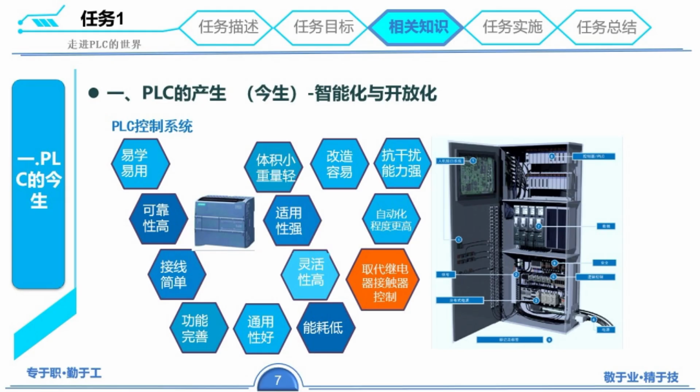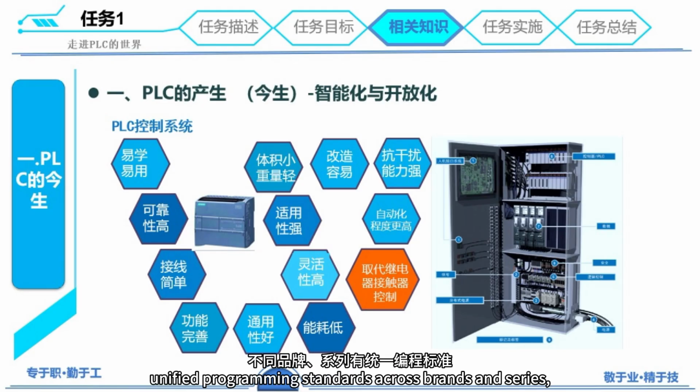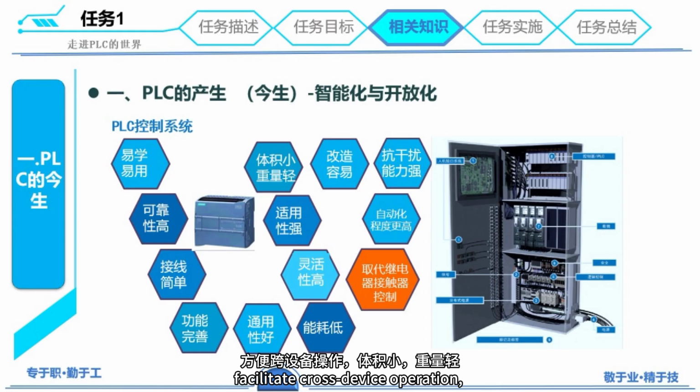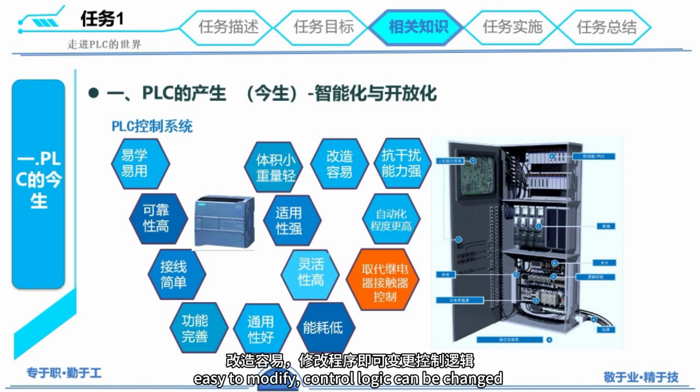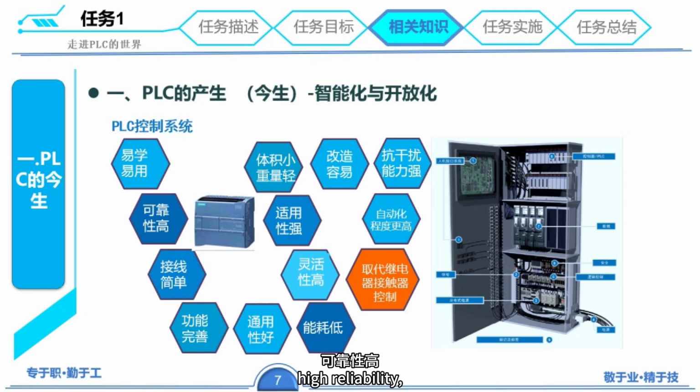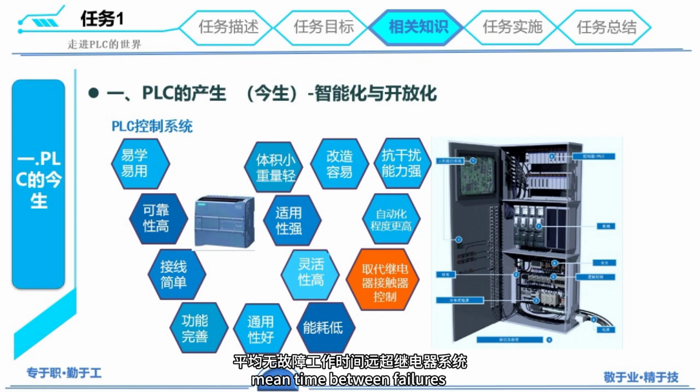Low failure rate. Good versatility. Unified programming standards across brands and series. Facilitate cross-device operation. Compact size, lightweight. Saves installation space. Easy to modify. Control logic can be changed by modifying the program. High reliability. Mean time between failures, MTBF, far exceeds relay systems, reducing downtime risk.